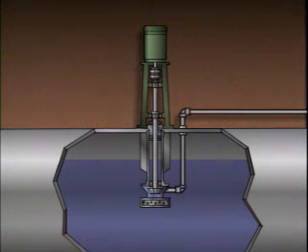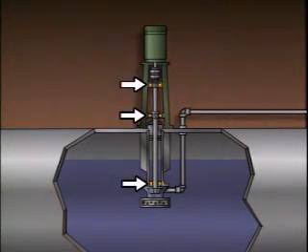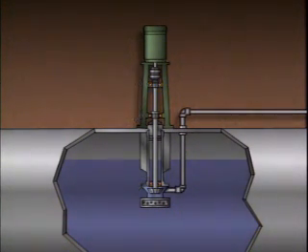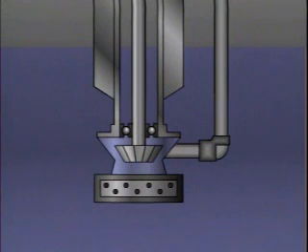so that the pump will operate properly. So several bearings are used to keep the shaft properly aligned. Now, on this pump, there is no suction piping. Instead, the suction of the pump is submerged in the liquid being pumped. The suction is covered by a strainer, which prevents trash or debris from clogging the pump and causing excessive wear.